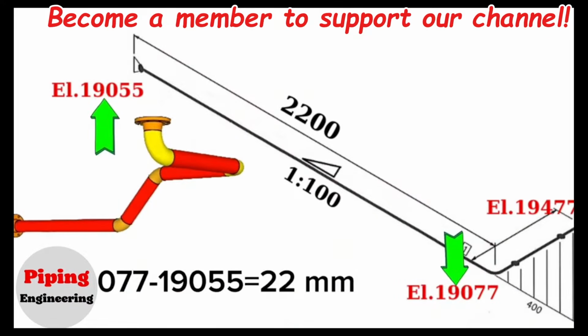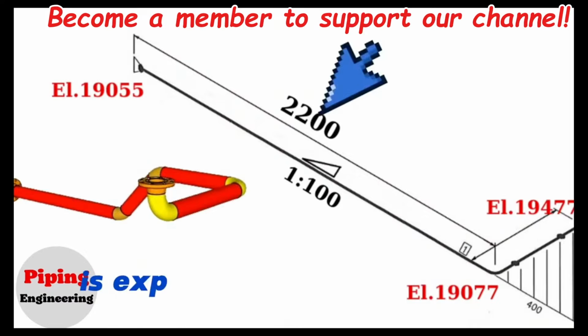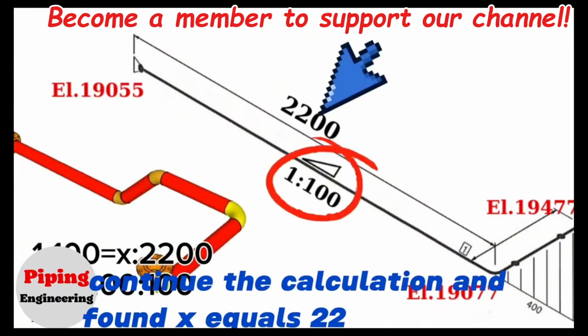Let's calculate with slope ratio now. In this pipe isometric drawing, the slope at a horizontal distance of 2,200 is expressed as a ratio of 1 to 100. 1 to 100 ratio equals x to 2200 ratio. Here x equals 2200 to 100 ratio. Continue the calculation and found x equals 22 mm. When you want to calculate a slope, you can use both methods on the piping drawing.